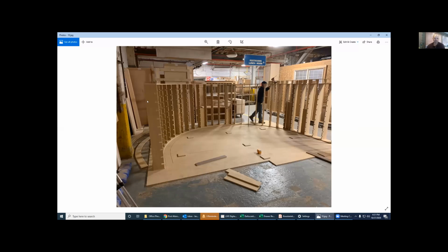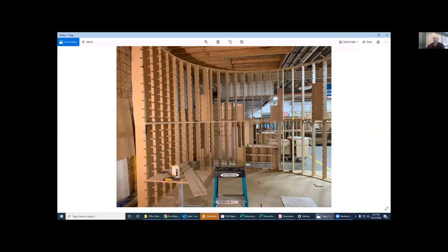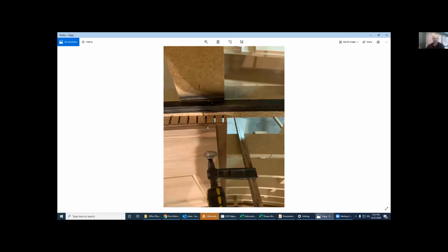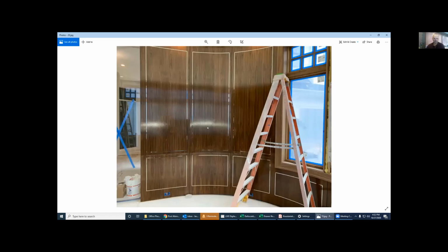And all the top plates, bottom plates, they get pretty slick. All those studs are basically identical, and then you've got unique plates and ribs. And all the ribs are identical because they're not identical to the studs. They're identical to each other, but they're inset. So they were on a different geometry. They were on a line that was snapped a 1/2 inch in from the face of all the studs and the top and bottom plate. So this was definitely the time saver of figuring out, oops, wrong way.